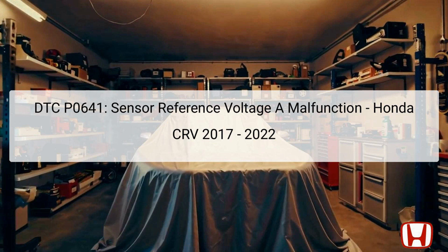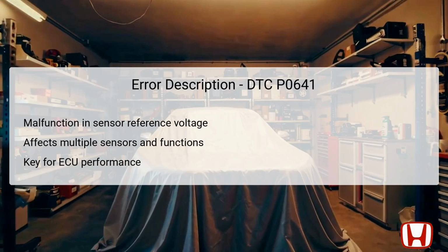Understanding the role of each sensor in providing accurate feedback to the ECU is vital for diagnosis. These sensors help ensure optimal engine performance by regulating fuel and air mixtures, providing critical data for transmission shifts, and managing HVAC operations. DTC P0641 indicates a malfunction in the sensor reference voltage A circuit, which supports vital sensors like the MAP and APP sensors responsible for various engine functions.